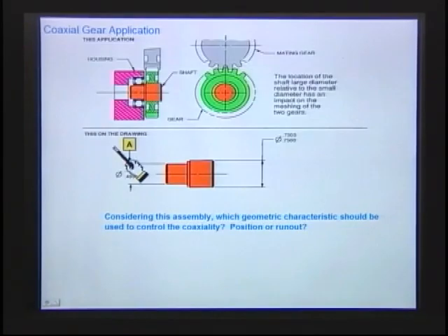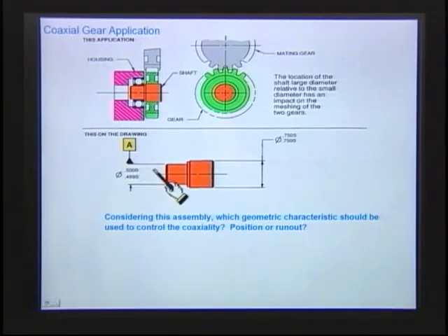All right, so on this drawing, you see what I did is I called the small one the datum. Now on this diameter, knowing our function, the way we're looking for this gear, what would you put here? Would that be a position callout, or would that be a runout? Now I hear a lot of people have this little saying, when in doubt use runout, but I wouldn't use that term at all.